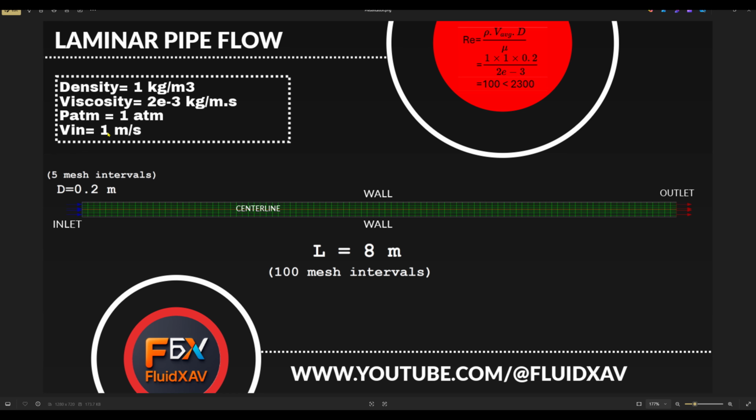You can see here. And then density is 1 kilogram per cubic meter, and the dynamic viscosity is 2e-3 kilogram per meter second. At the outlet, we will set the static pressure to 1 atmosphere, and the pipe wall will have a no slip condition. Using these values, the Reynolds number is 100, which is far below the 2300 transition threshold, confirming that the flow is laminar.